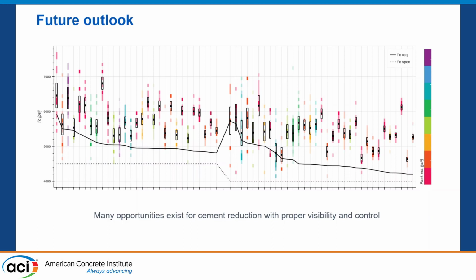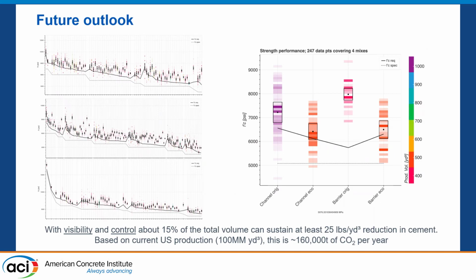So you can do this and look over your entire catalog of mixes. This brings up a lot of questions. Why do you have 20 different 4,000 mixes? Could you get around with maybe 2 or 3? There's absolutely a need for more than one because there are different situations for these to go into. But this allows you to look at some of these way over-designed ones, these ones here, for example. Are they using a special aggregate? Why is the cement efficiency so high for those? You can really start to look through your catalog and optimize your decisions that way.